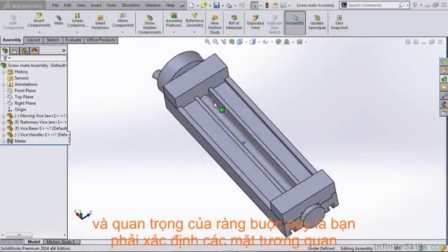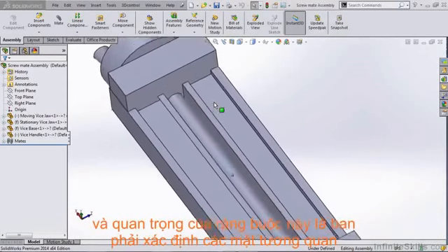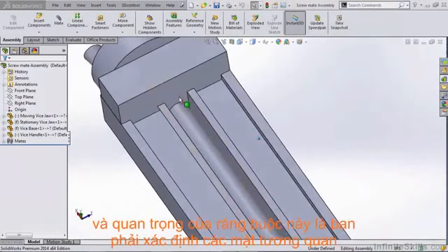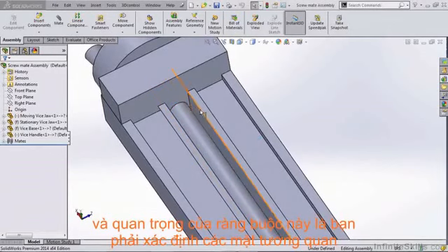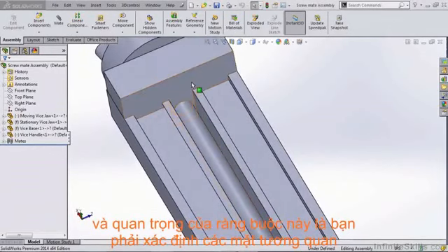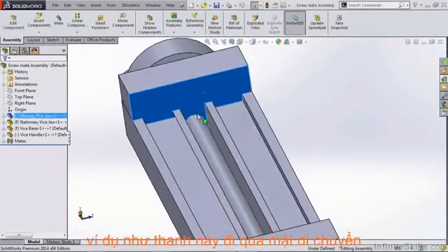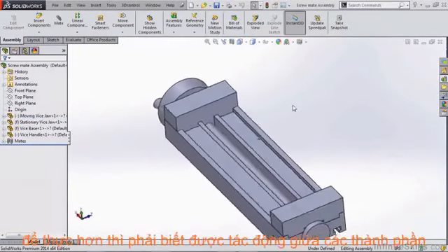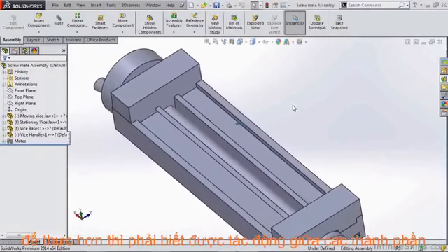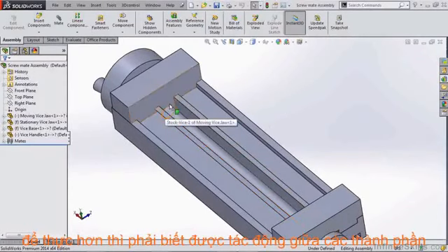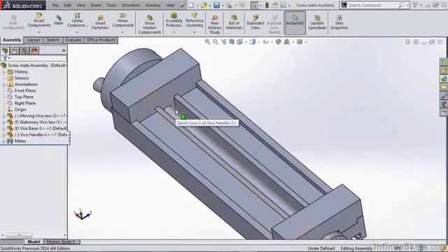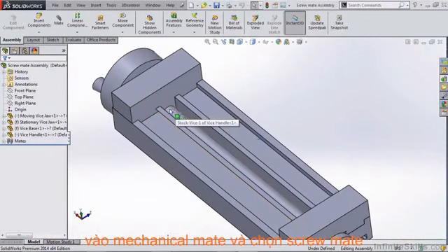Now, there are a few things that you need to note when you're creating a screw mate assembly. There needs to be a common face between the two. For instance, this vise piece has to have a hole through it where the threads will be engaged. This is true when you're creating these assemblies for a realistic purpose. So you just need to be sure that you have the proper interaction between your components. Let's take a look at applying this mate.